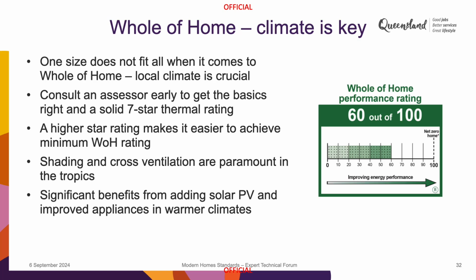Whilst NatHERS whole of home is flexible, you can select the group of appliances, whereas in some of the other compliance pathways, it's not as flexible. It's really important to get an energy assessor early, so to get the basics right and have a really solid thermal star rating first. And as I noted before, with the solid thermal star rating, that benefit then flows through to your whole of home budget, with the minimum being required of 60 out of 100.